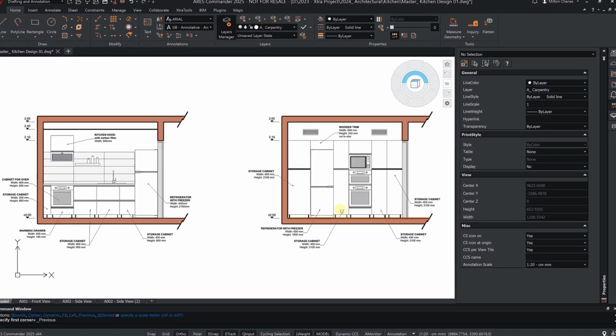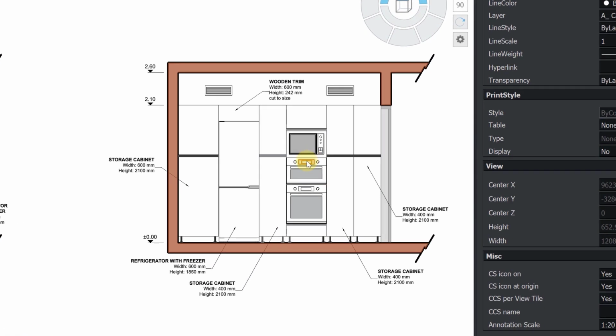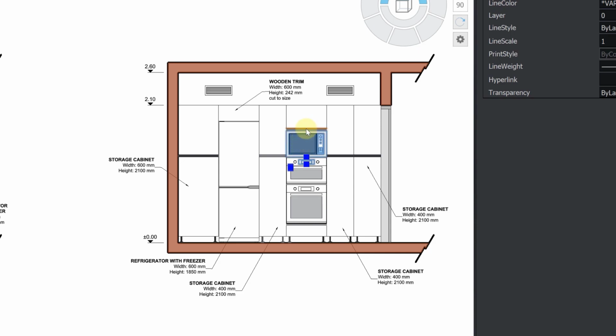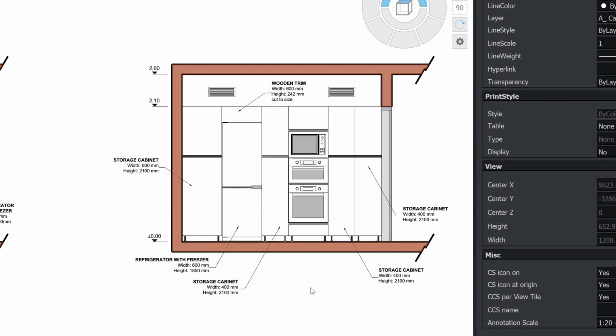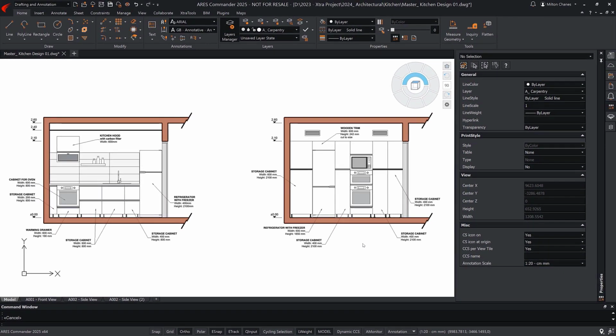After all this, we should rebuild all the blocks we have exploded. While this approach is acceptable for simple cases, it can quickly become a nightmare. And in our example, we would even break our dynamic block while exploding it. The new block structure palette makes it much easier. So let's go back and see the difference.